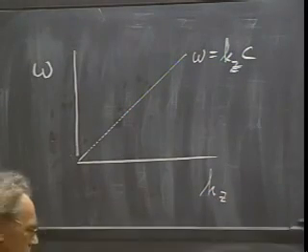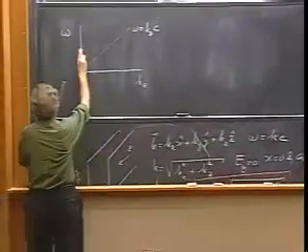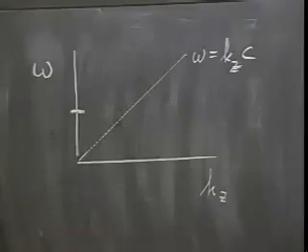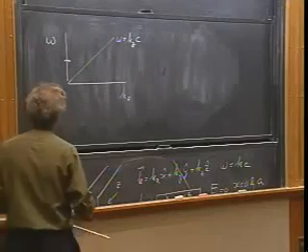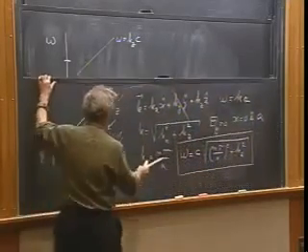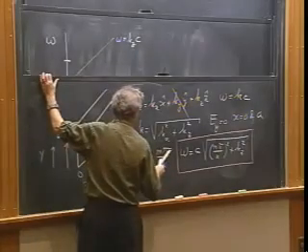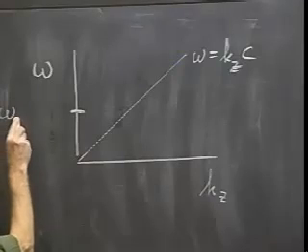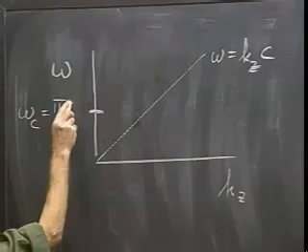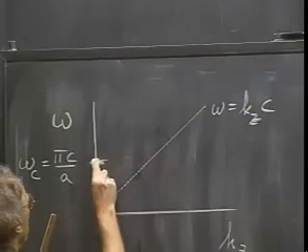However, this is different because of this. And so now you have here a frequency which is the lowest frequency possible for which radiation can actually go between the plates. And this then is the case for m equals 1, and omega is then c times pi divided by a. And so here, for omega, that is the cutoff frequency, is pi times c divided by a. And if I plot then that curve, you get something like this.